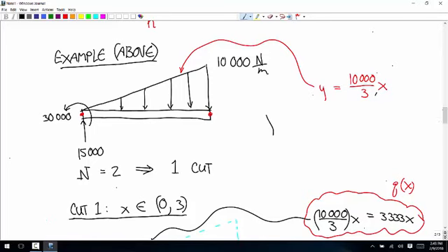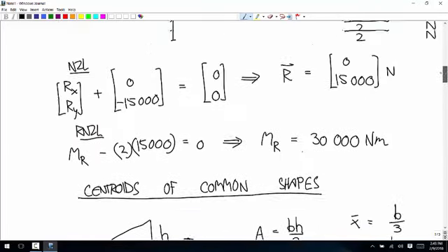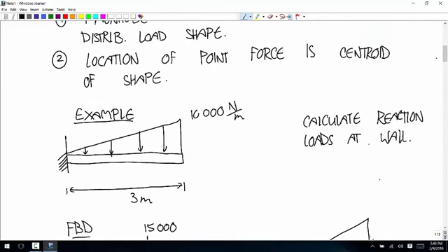And that is because you get 3 variables of load on the left side because of the fixed joint. You get 3 more variables on the right side. You only have 3 equations in 2D from Newton's laws. So you'd have 3 equations for 6 variables, and using statics, you can't solve that. That's called statically indeterminate.